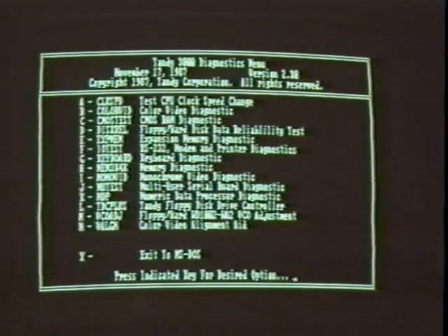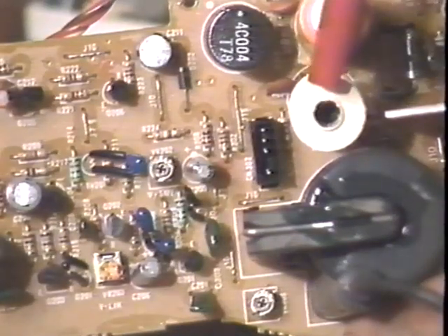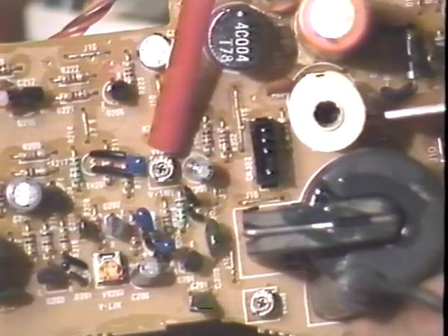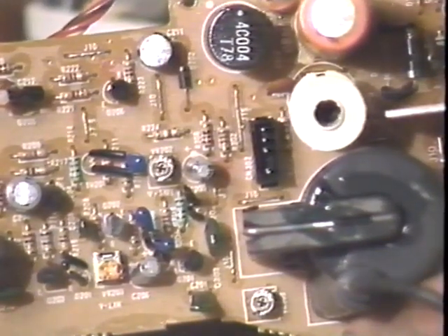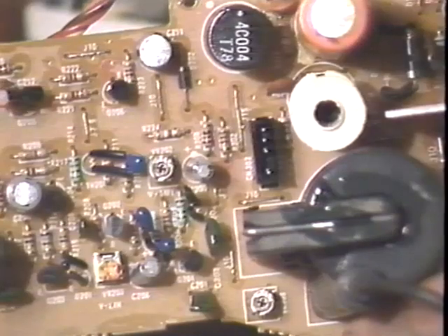The sweep circuitry usually contains several adjustable components that allow you to align the monitor for a stable, correctly centered and sized display. Adjustable coils are used for some of these alignments, and variable resistors, sometimes called pots, for others. Potentiometers are also sometimes used to adjust power supply outputs of standalone monitors.